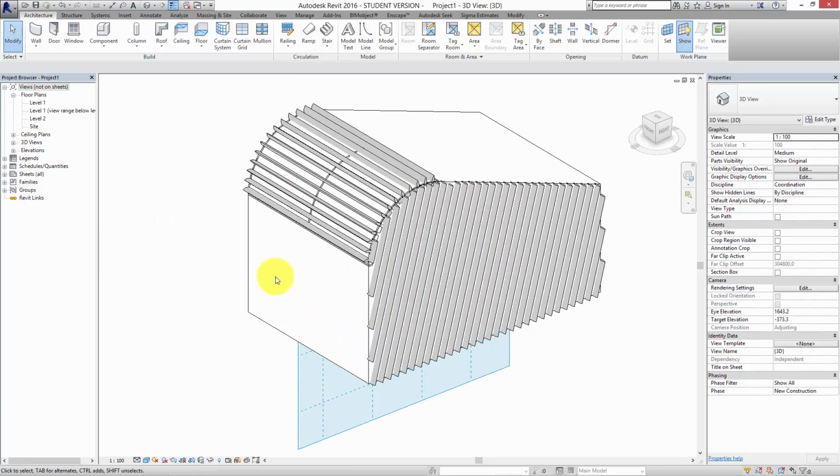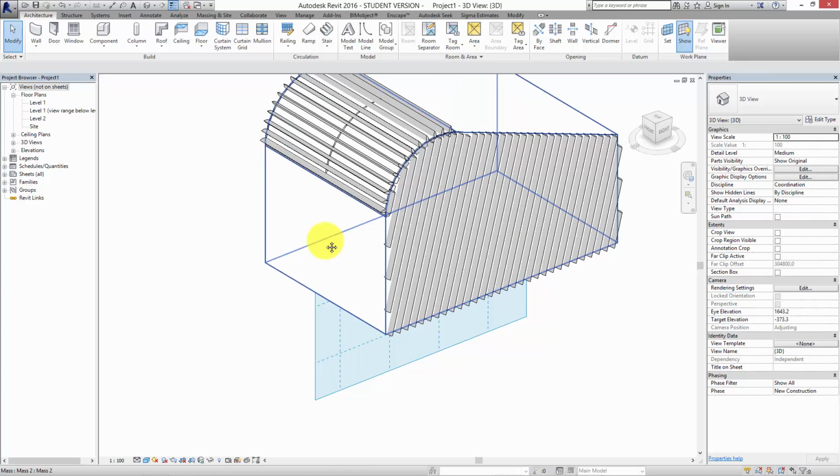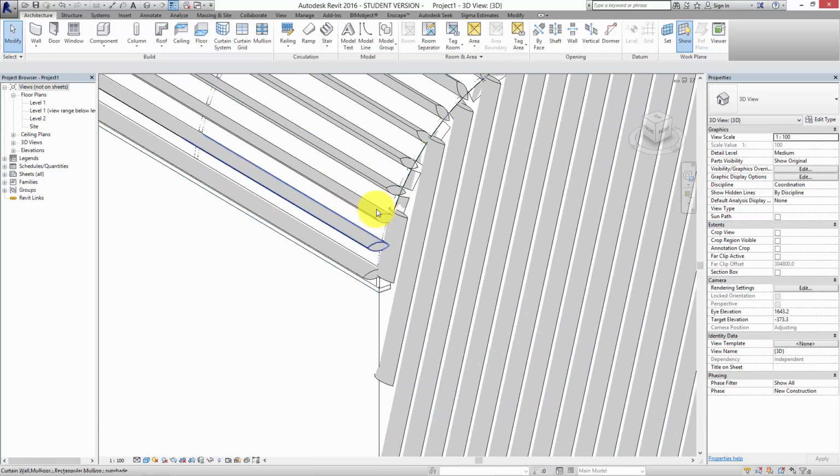If you wanted to make an extremely complex curtain wall, you can actually add curtain walls inside curtain walls inside curtain walls. So every time you have a panel, which at the moment I changed to air, if you remember, it started off as glass, but this curtain wall panel, you can also actually assign a curtain wall to the panel as well. So you can add more and more and more detail as you go through. If for example, I want to use like this space here, and then this space here, and then add something else.